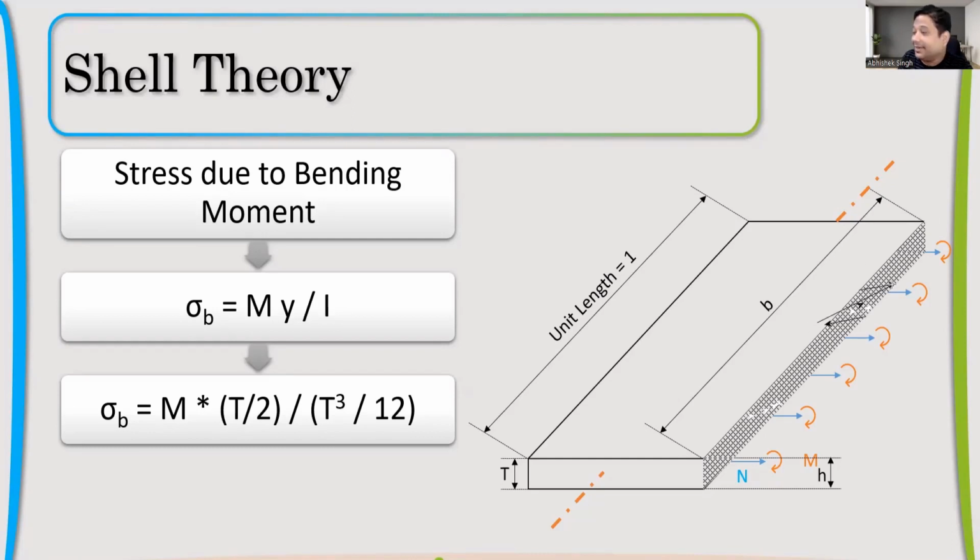Bending, any cantilever when we did, right? If I'm considering that it's bending like this, the top is getting tension. So there will be the extreme force, and then it will slowly go down to become 0 at the center, then again go into the compressive direction. And what will be the behavior of the membrane force? That will be exactly equal across the section, right? Equal across the section. So because of moment, there is stress generated in the same direction, and also because of membrane force.